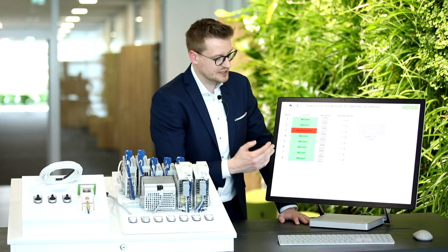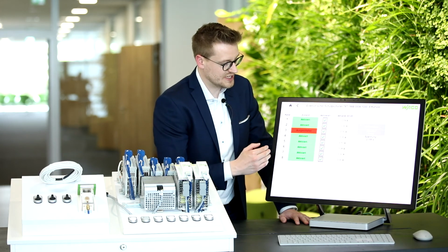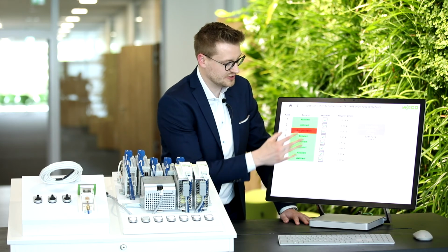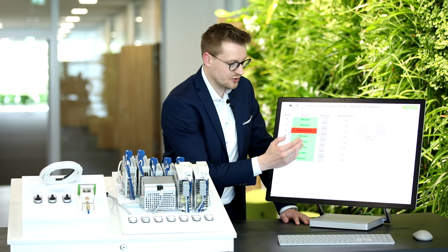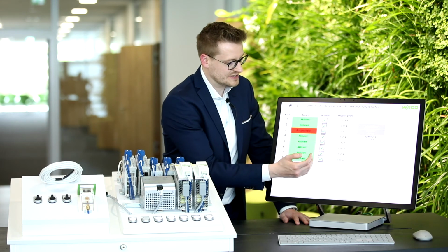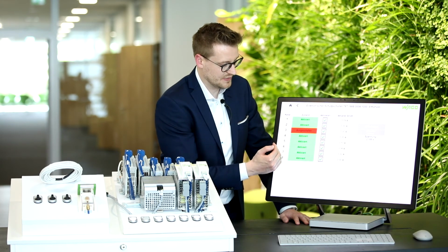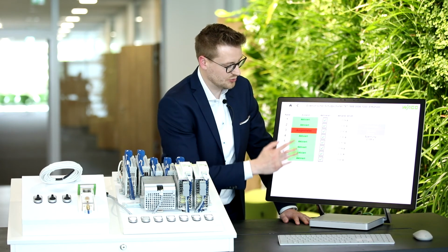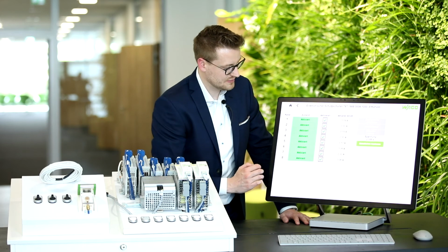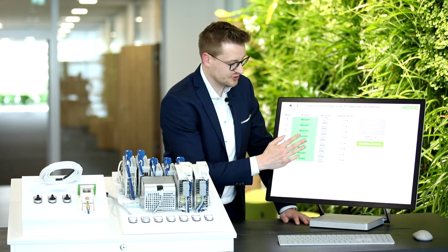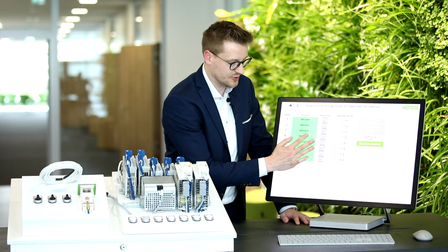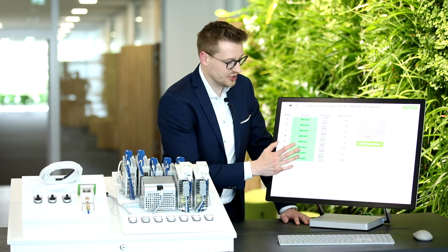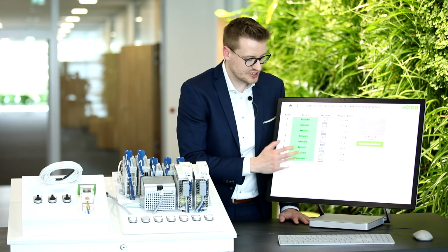And now we have the impulse sequence, which is sent to our I/O system. After the I/O system gets the information of the status, it will send the configuration we have done right now to the electronic circuit breaker. This may take a little bit of time, but we will see right now. So right now you see the electronic circuit breaker channel 3 is activated. This is a little time delay we have, but we can use this.